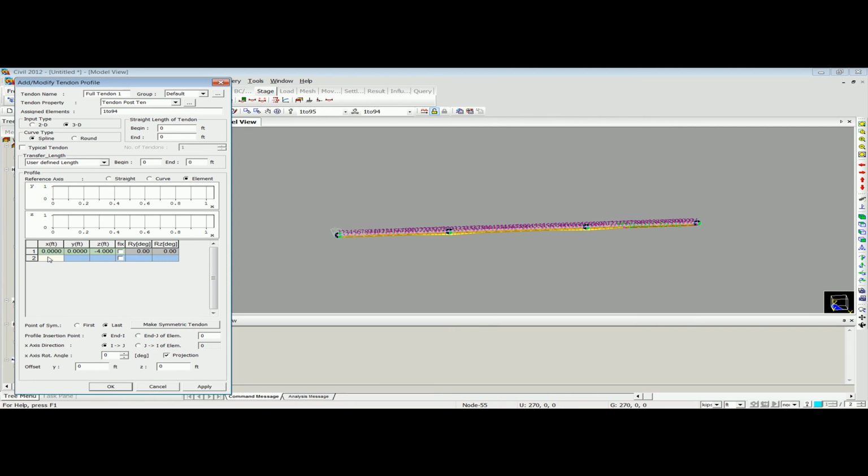At x equal to 145, the first pier, the first mid support, it's gonna go up. At x equal to 145 plus 90, it's gonna be 235. It would come down again because of the positive moment reason.